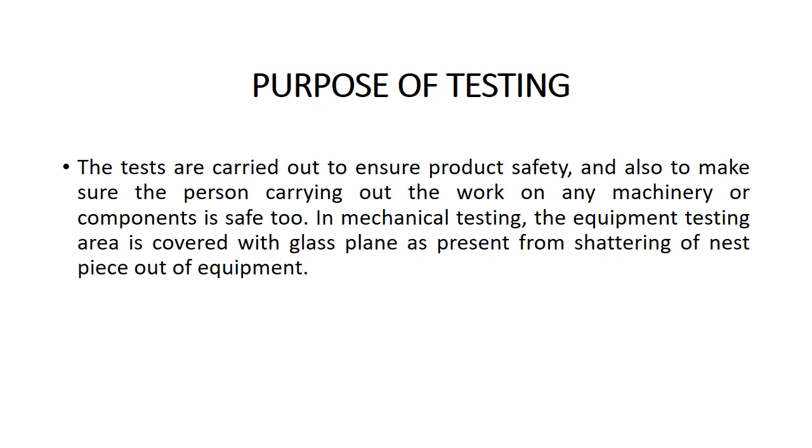Then non-destructive testing. It is a test to determine, detect, characterize or measure the presence of a damage mechanism, for example, corrosion or crack. Many types of NDT technique are capable of locating defects and determining the features of the defect such as size, shape and orientation.